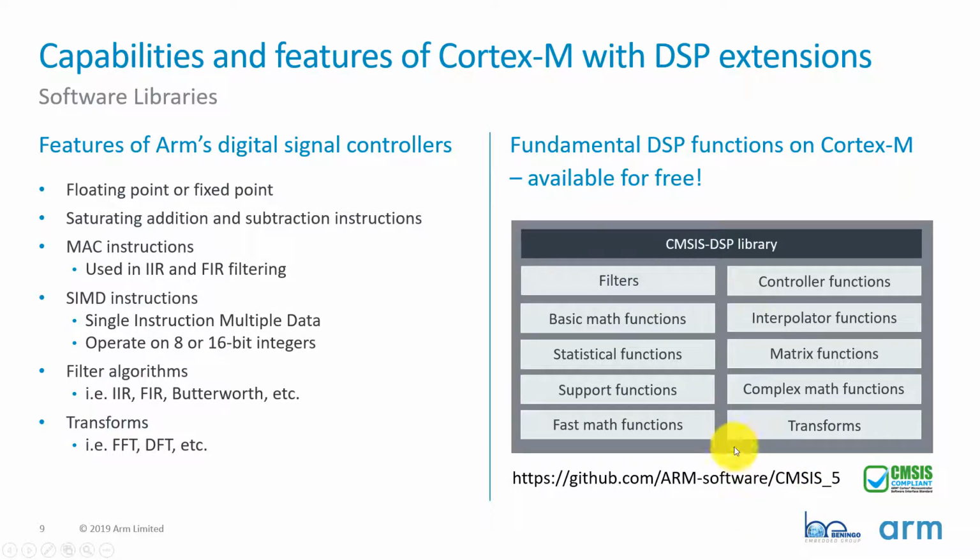It actually includes more than just the DSP library. It includes all of CMSIS. But from there, you can get the CMSIS DSP library and dig through and see all the features and functionality that's there. There are over 60 different functions to help us as developers more easily implement our digital signal processing algorithms. So you'll find that, for example, doing an FIR filter is as simple as creating the table of coefficients for our filter, and then just passing the data into a FIR function, and then at that point, it automatically does all the math behind the scenes for us. So it really simplifies development.